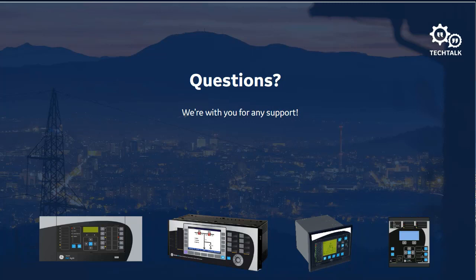If we're looking at a meter and we see negative sequence current is larger than the positive sequence current, that meter has some wiring errors on it. Or maybe it's possible a setting error, but more than likely it's got some wiring errors on it. Or a relay, a relay would do the same thing. So we would never expect the negative or zero sequence currents to be larger than the positive sequence quantities.